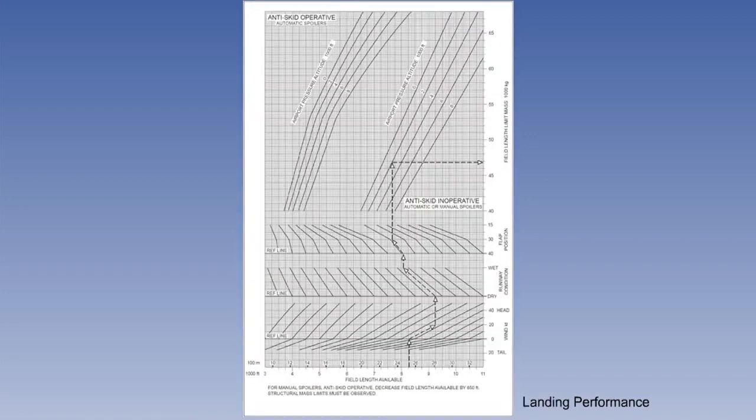In all cases of contaminated or wet runways, there will be a percentage factor to be added to the calculated performance distances. EU OPS regulations demand that operators ensure that the distance available for landing is at least 115% of the distance required, but this may be reduced if the relevant flight manual contains specific information on these conditions. This lesson need not detail all the factors applied for the various conditions, as these are all covered in the performance syllabus.